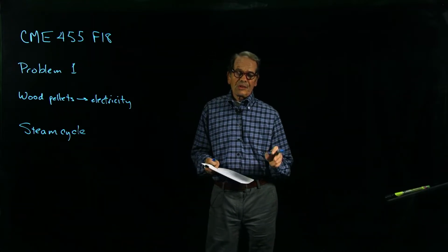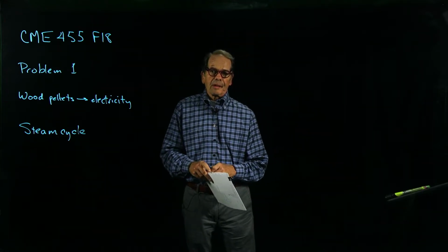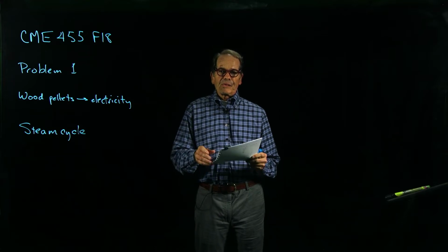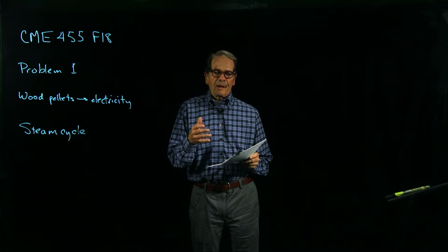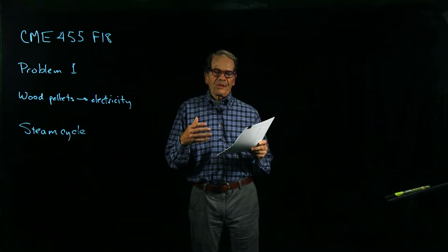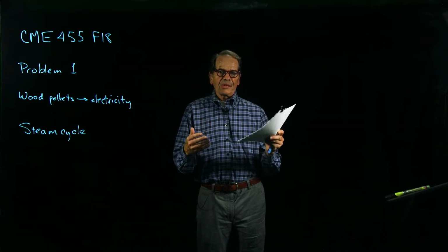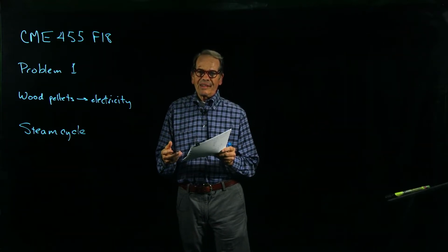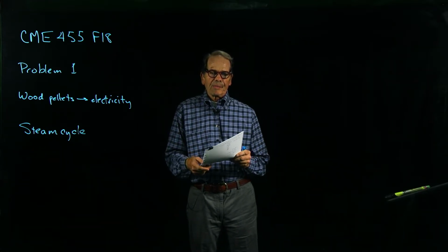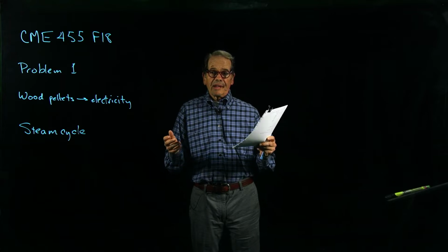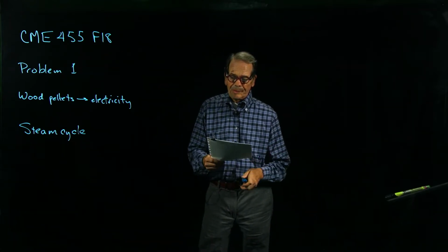The reason we start with this problem is because we really have to solve it by hand first before we put it in the simulator, in particular because we typically know what the enthalpy and the entropy is of the various streams, but we need to convert that into pressure, temperature, and flow data for the simulator. So we're going to do the theory and some of the discussion first, then we will move to the simulator.